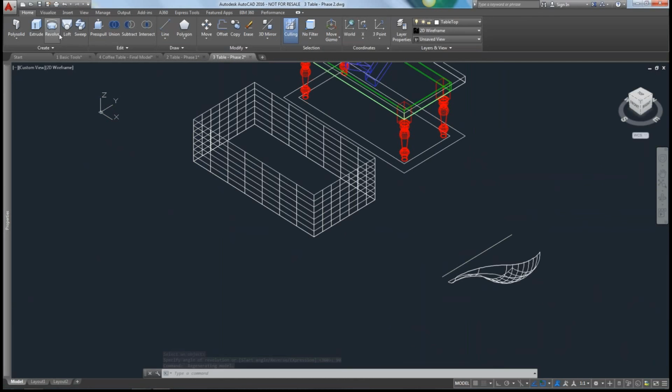I almost want to say that Loft will do the same thing, so you want to look at the mode. There's also something I run into while doing 3D drafting: you may have changed that option and all of a sudden you're doing a closed line and you get a surface. Just remember you can go back into the command and change it. It will remember your last objects.